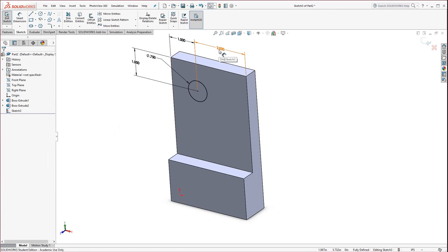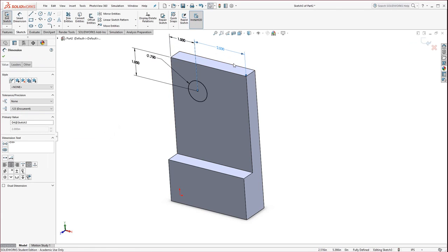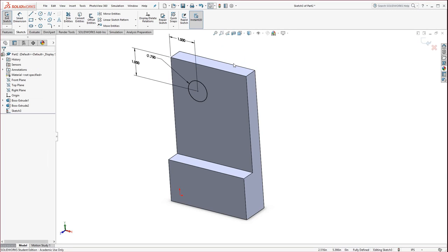So I don't really need that 2-inch dimension. I'm going to click on it. And this is how you delete things. You could delete lines. Usually if you delete lines, select them from the center of the line, not from the endpoints. It doesn't delete endpoints. You have to delete the whole line. So in this case, we just select the dimension, the actual numbers, and hit delete on your keyboard. That's right above the arrow keys. DEL, delete. And it should disappear.